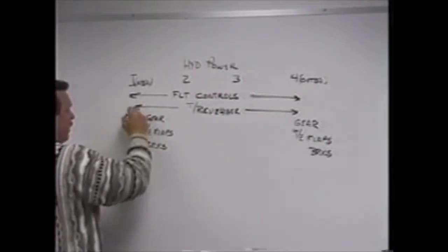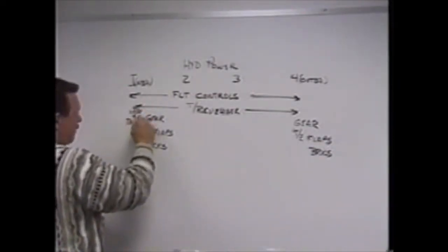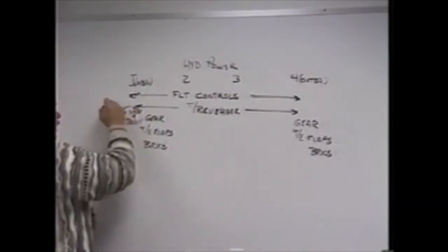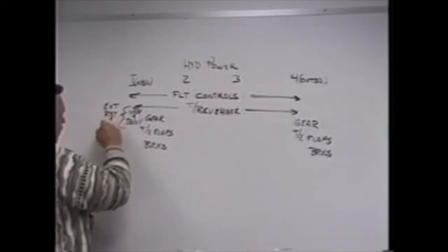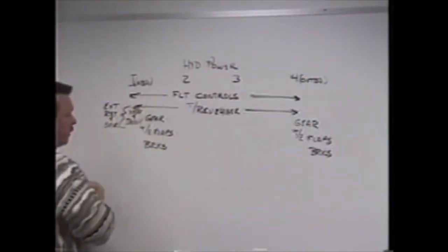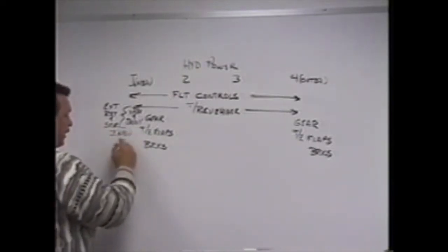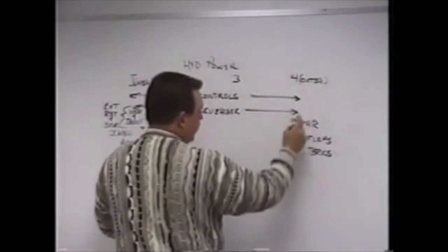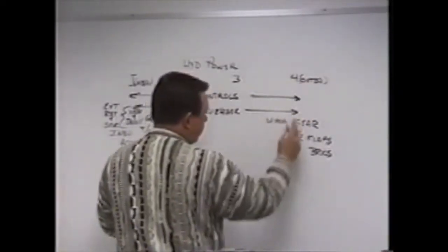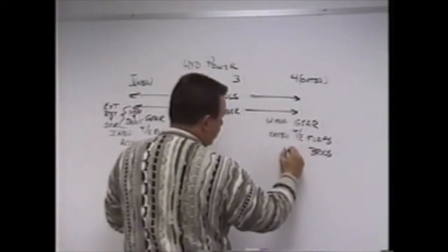Inboard gear, that would be the nose and body gear. And you're talking the normal extension, retraction, and steering for both your nose and body gear. Inboard trailing edge flaps, and alternate brake system. Outboard gear, that's called the wing gear, outboard trailing edge flaps, and normal brake system.